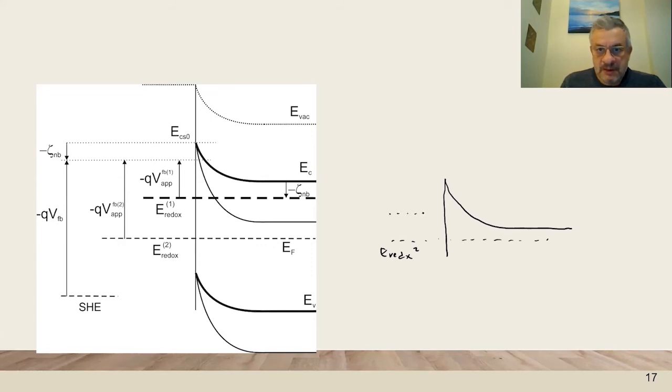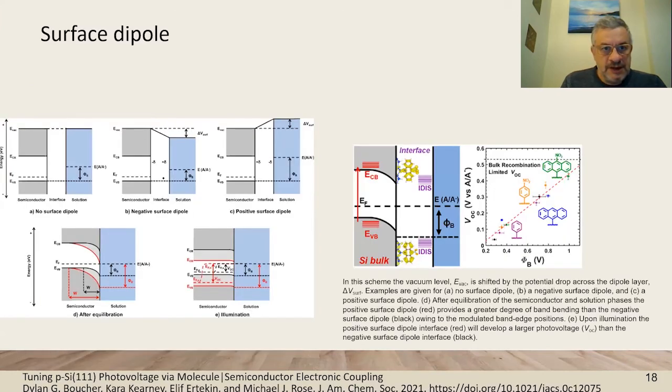And if we change the electrolyte and make a higher one, then this will come to the other equilibrium, and we will have a reduction of the interfacial barrier. Also in the semiconductor electrolyte interface, we can have the surface dipole, and the surface dipole is going to change the alignment of the energy levels between higher or less high barrier depending on the amount of interfacial dipole.